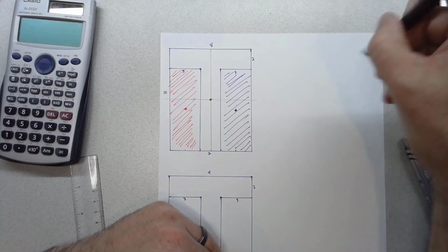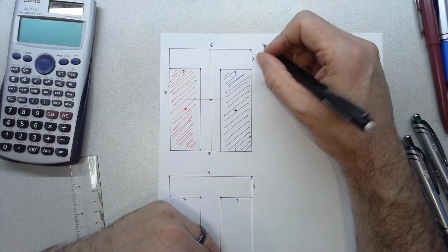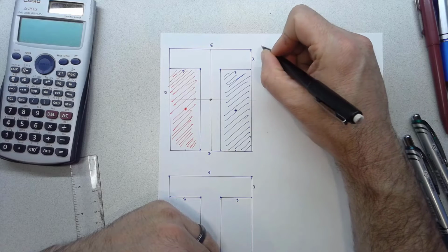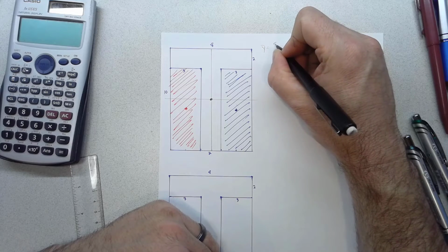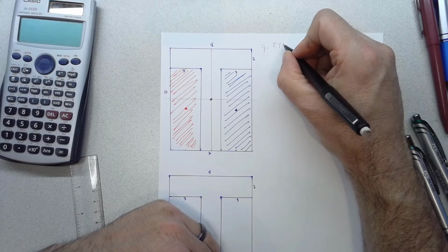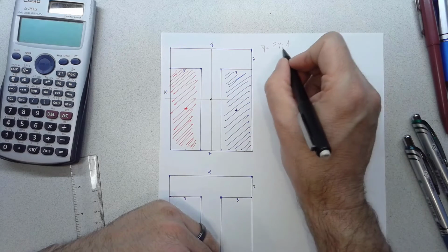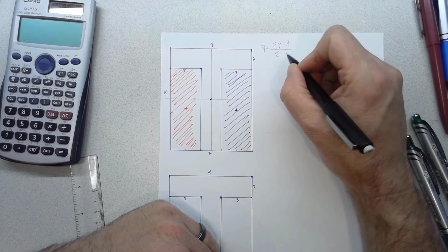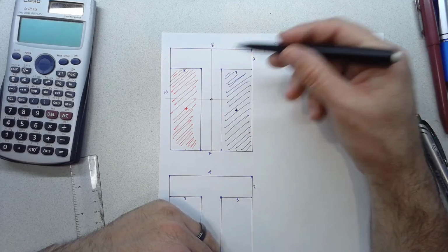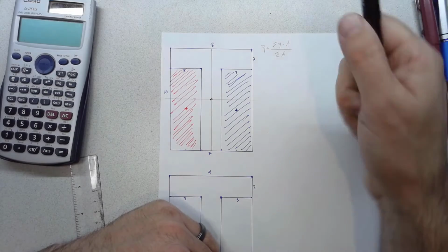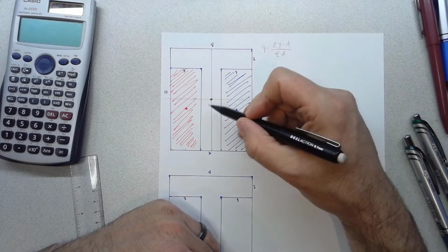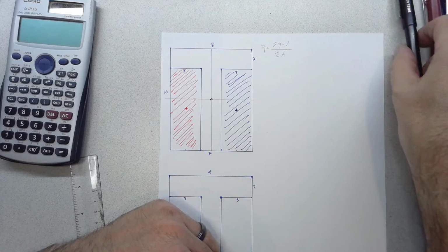So remember, the formula for finding the centroid of an object is y bar is equal to the sum of the individual y's for each component piece times the area of each component piece divided by the sum of the areas. Another way you might see that is as a weighted area, or first moment of inertia, but that kind of confuses it with I, so we usually just call it the centroid.